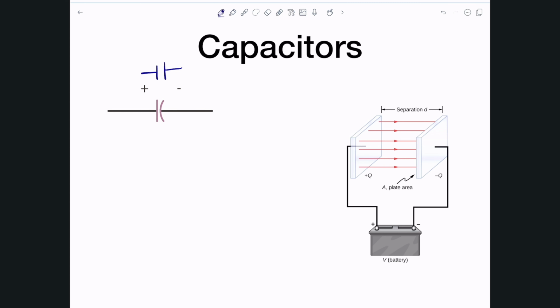But how do we measure them, or distinguish between different capacitors? Capacitors have what we call capacitance, usually termed C. You can compute C depending on the type of capacitor you use, and the rule is simply C equals epsilon times A divided by d, where A is the area of the plates, d is the distance between the two plates, and epsilon relates to the dielectric or insulator material you put in them, called permittivity. This is not very interesting. If you're building capacitors, this is what you focus on, but for circuit analysis, we're just going to assume that we have a capacitor, and I'll give you what the capacitance is.